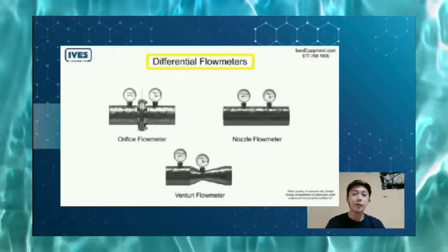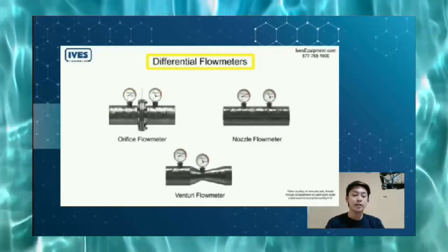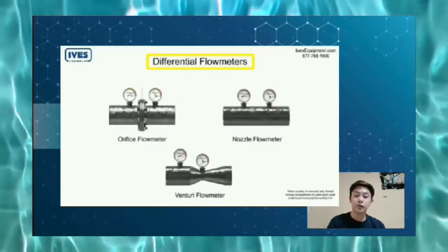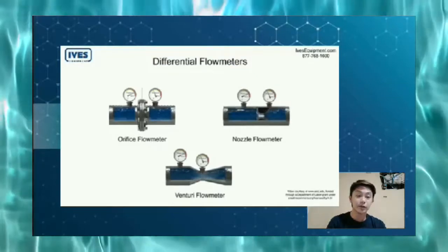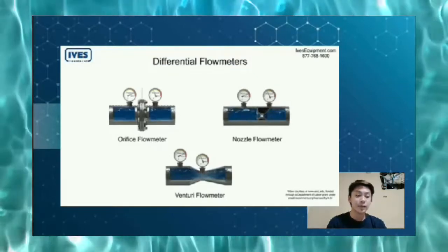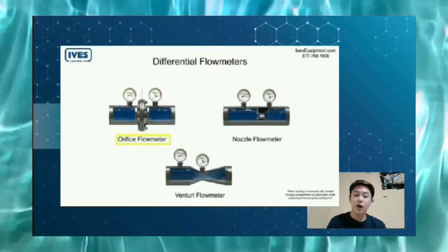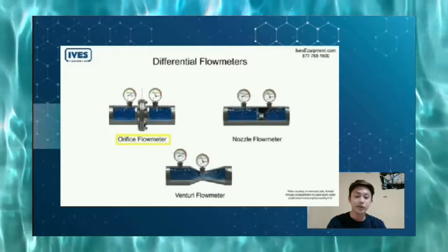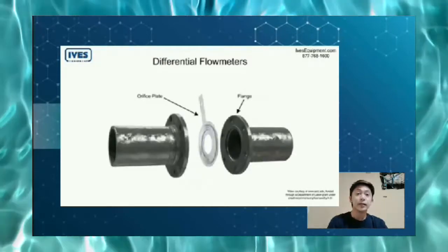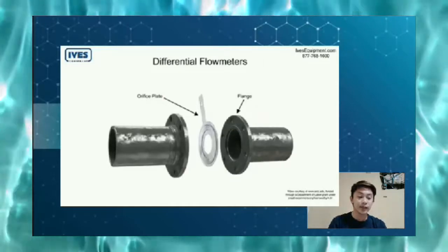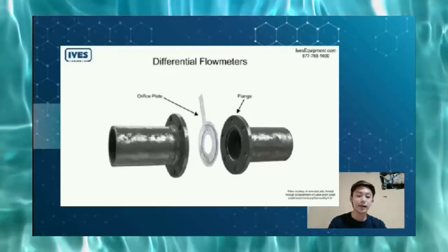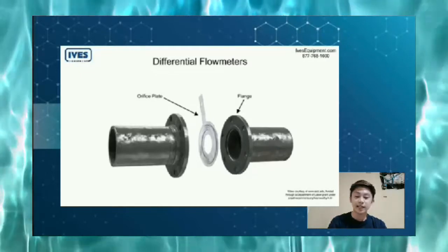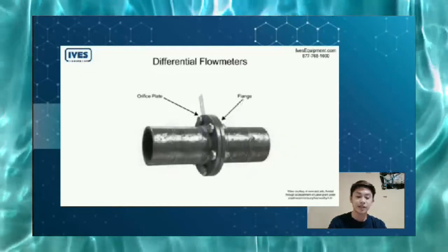The differential flow meter is the most common device for measuring fluid flow through pipes. Flow rates and pressure differential of fluids such as gas, vapors, and liquids are explored using an orifice plate flow meter. The differential flow meter, whether venturi tube, flow nozzle, or orifice plate style, is an instrument that is installed between two pipe flanges.